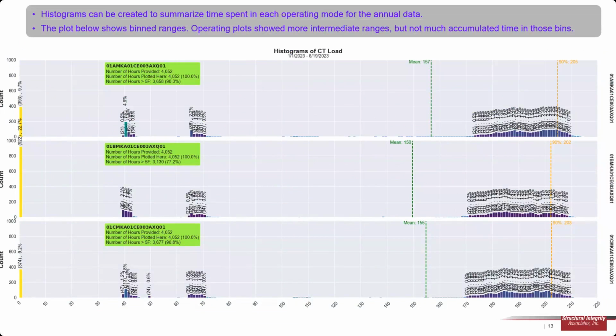I guess I'm going to get through a little bit of this, but this is plotting that load versus time on histograms instead. So you can see when we're looking at how Duke operates the unit, one of the things we're looking at is what operating bins, low loads, intermediate loads, high loads, with or without duct burners, are going to be the most damaging versus time. And you might think for creep, it's generally going to be the highest temperatures, hottest pressures, but that's generally not the case when you're dealing with attemperators and bypasses and intermediate conditions between those.